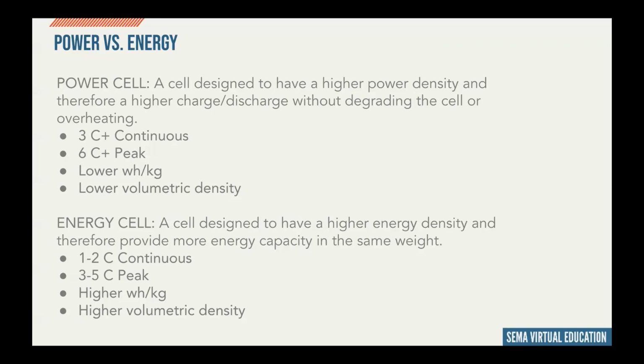In the future, those cell technologies will be much more available, whether it's graphene-based carbon battery cells that utilize electrostatic technology like ultracapacitors, or a new lithium chemistry like lithium sulfur that provides significantly higher energy densities without sacrificing power or discharge. But with the current technology we have today, this is typically what we see in a power cell versus an energy cell.